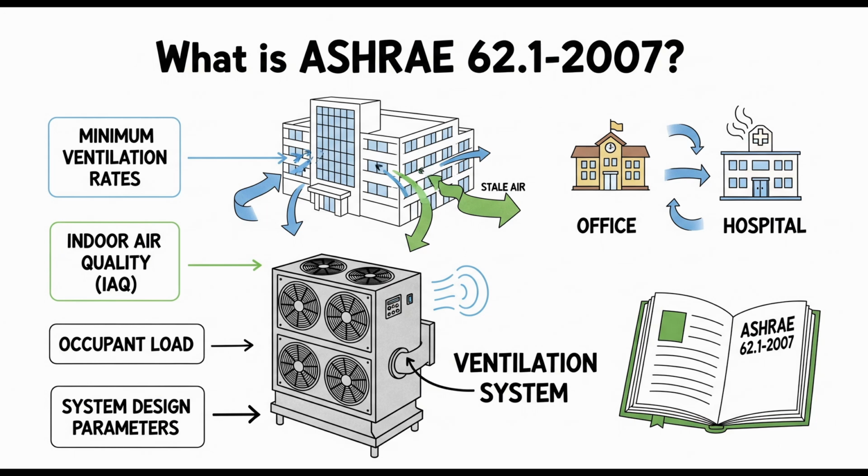You also have to test drain pans under cooling coils to make sure they actually drain properly. Standing water is a big no-no for mold. The system needs to be clean inside before it's officially started, and you test the outdoor air dampers to make sure they open and close correctly, controlling how much fresh air comes in. Seems like a lot of checks, but essential to know it works right from day one.